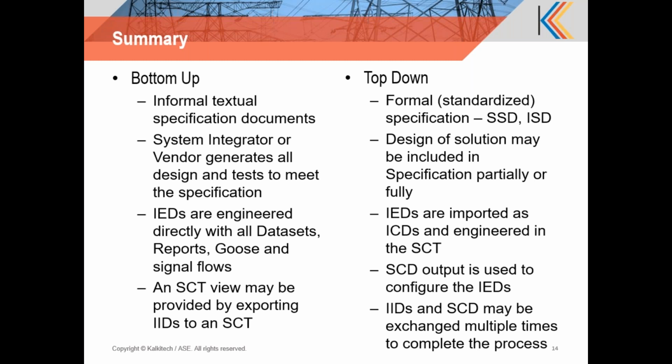Fixed offset is a service support that you declare, basically to understand if the GOOSE allows you to encode the data in a slightly more efficient manner. For example, in the typical encoding of GOOSE, a 32-bit integer value like the state change number or the sequence number is encoded differently based upon the value. To send a value of 0 or 1, it does not use 4 bytes or 32 bits, it just uses 1 byte.